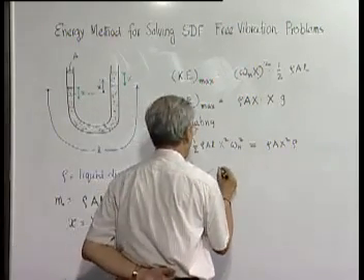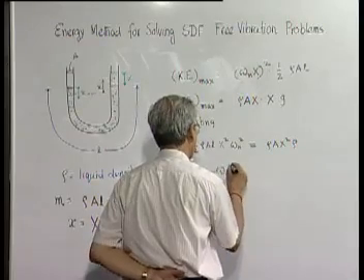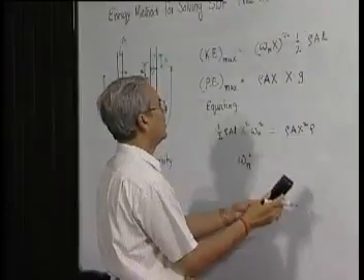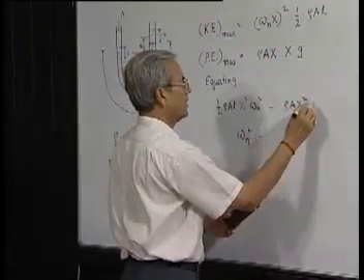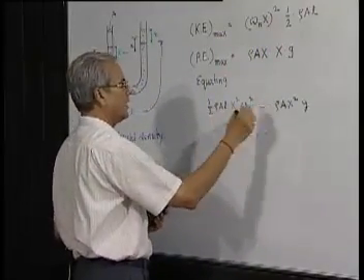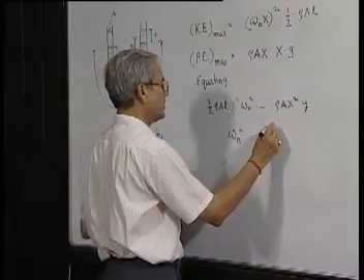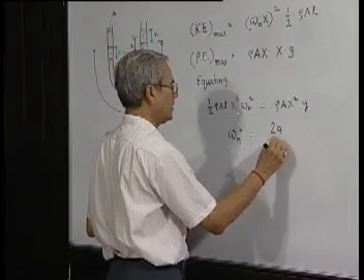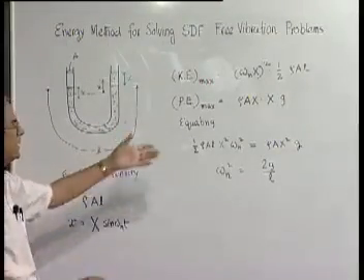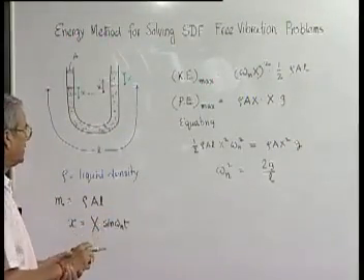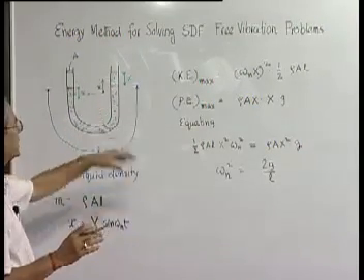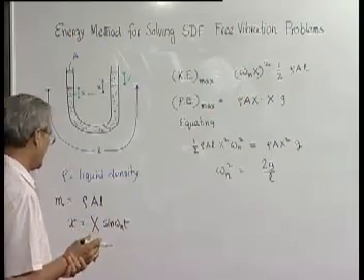So, here we get an algebraic equation in omega n, which tells us omega n square is equal to, X square goes, A goes, rho goes, what remains is 2g over L. So, this is again so nicely done using this principle of energy, where we equate the maximum kinetic energy with the maximum potential energy.